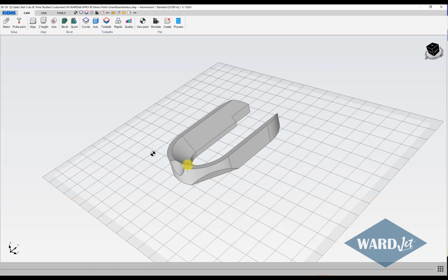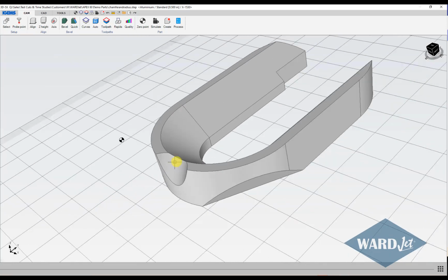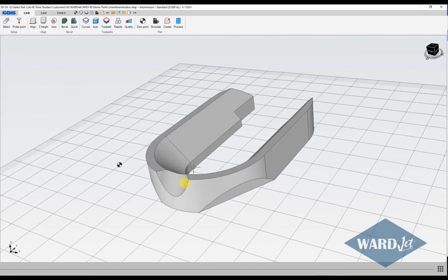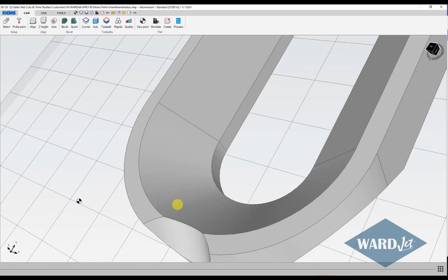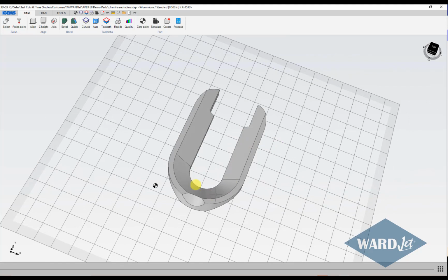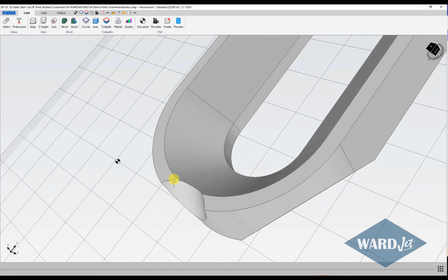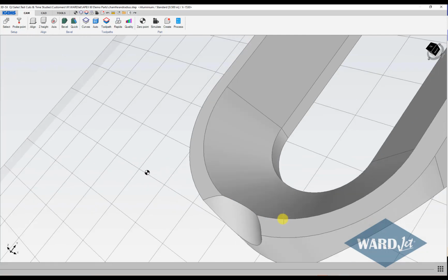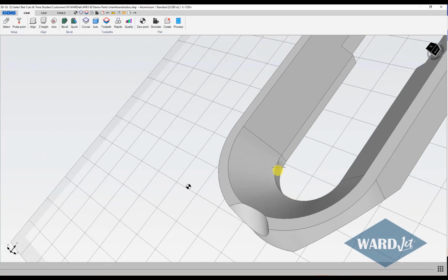So next we're going to have to figure out how we're going to attack this. What makes this one a little bit interesting is we've got some missing edges here. So for example, on this bevel cut here, which is essentially a fixed bevel, but we're swinging the C-axis around as we're going around here. We could pick this edge, this edge and go like that, and then correspondingly choose this as our bottom edge.